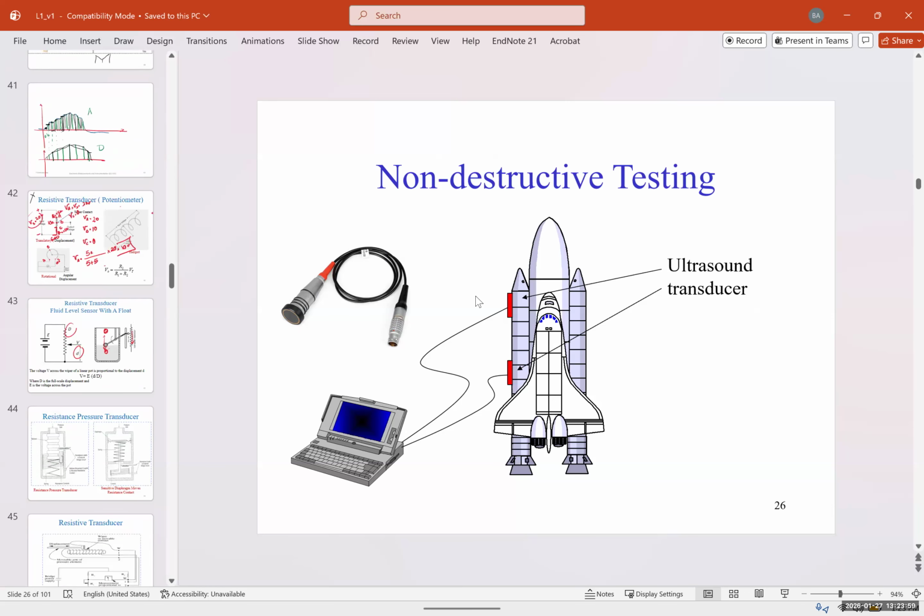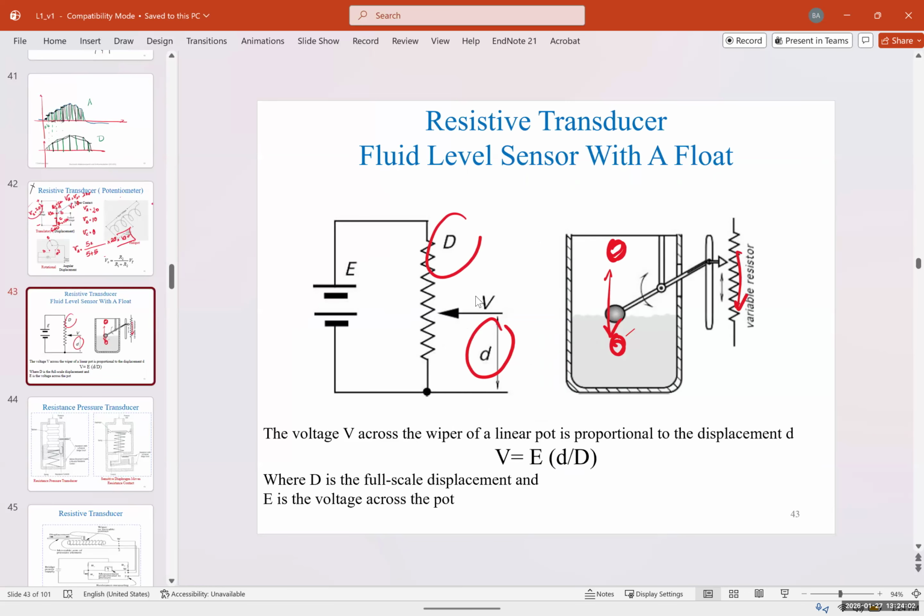One thing that I have personally experienced is, for example with this type of sensor, if you're going up a steep hill, then the liquid moves to the other side of the tank, and suddenly this drops. And you may think that now the tank is empty or full. If you're on an incline or park somewhere, this sometimes is not that accurate. But other than that, it's very reliable, very cheap, and it's going to last a very long time.